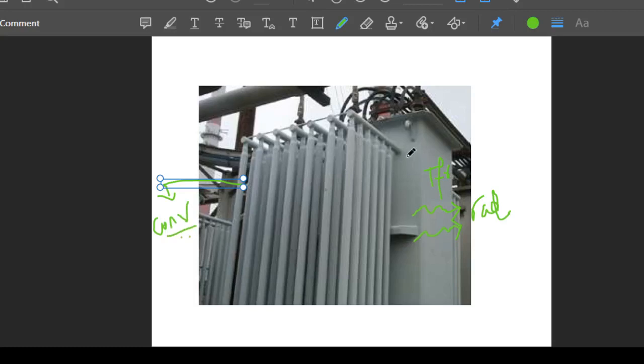But you should also keep in mind, these sets of tubes are actually acting as a barrier to this chamber. So the radiation which is free to happen is getting affected by this tube arrangement. But even so, convection is helping us to provide an improvement in the dissipation of heat.